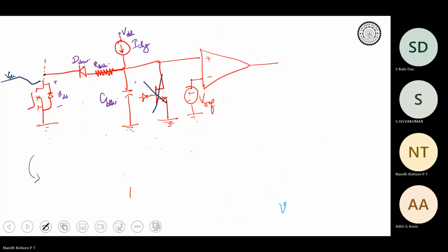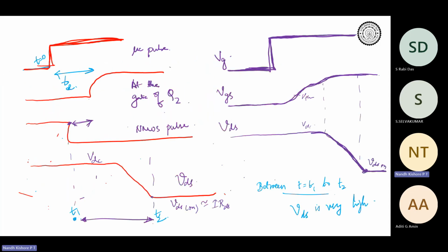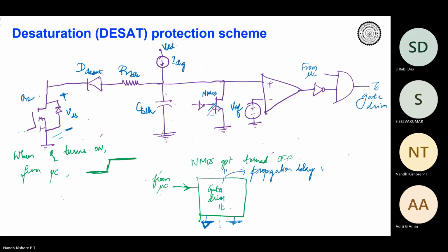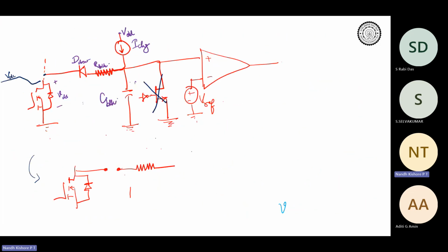The diode is reverse biased, voltage is still high or it is falling, but still we know that the diode will not get forward biased until the voltage at this point exceeds your VDS, right? So diode is obviously reverse biased right now. Okay.